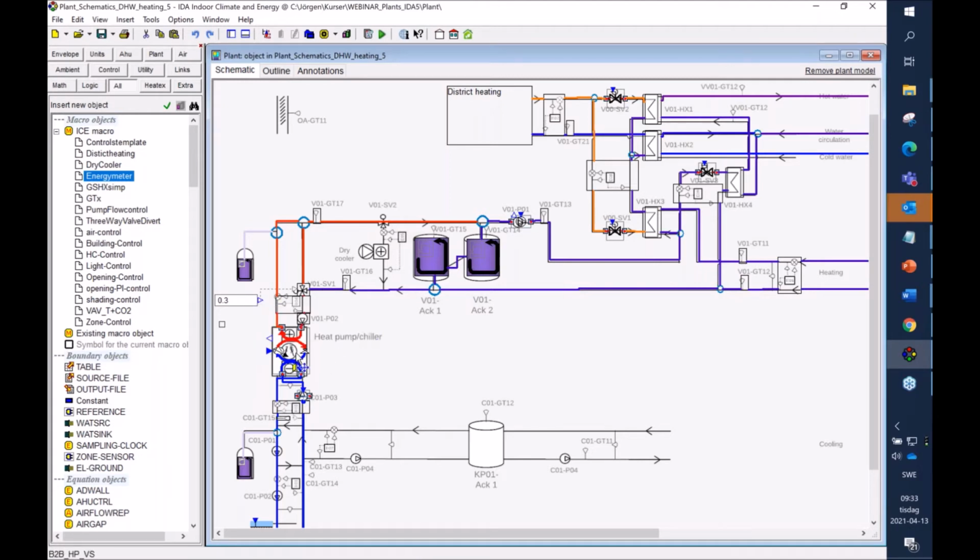And the opposite, if the heat pump is off, no flow in this circuit, the heat can be taken from the tanks in this direction with a backwards flow. So it's really useful, and that's due to the new brine node and the tank with bidirectional flow.